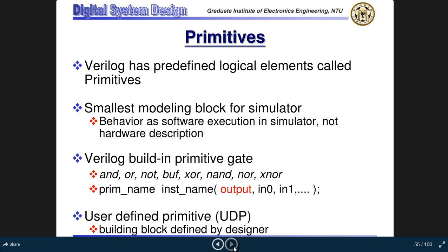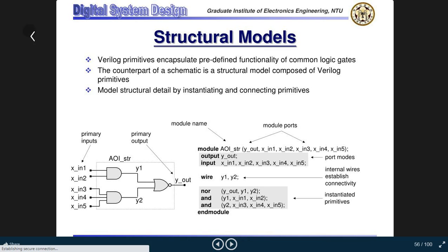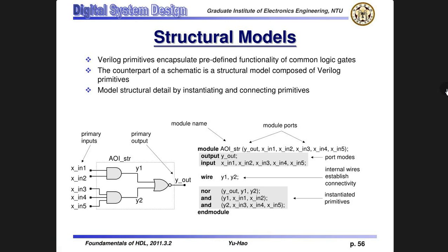Okay, let's go to the next slide. Structural models. Verilog primitives encapsulate predefined functionality of common logic gates. The counterpart of a schematic is a structural model composed of Verilog primitives. Model structural detail by instantiating and connecting primitives.